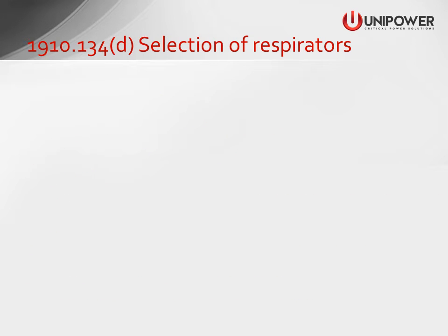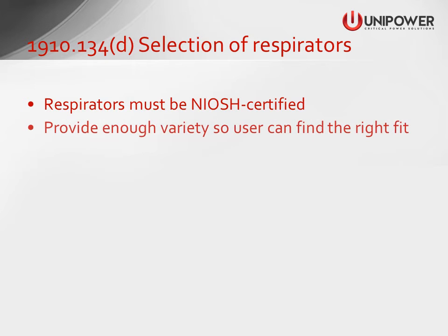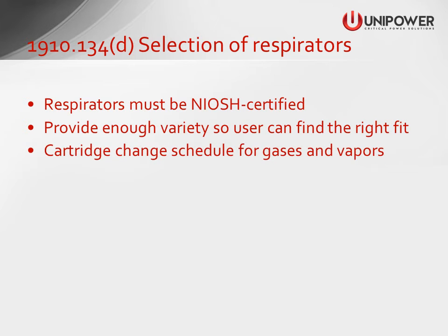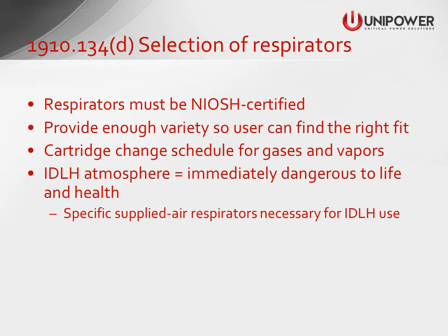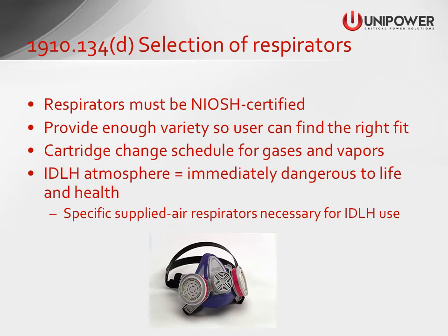Section 1910.134D speaks about the selection of respirators. Respirators should be NIOSH certified. The company should provide enough variety so the user can find the right fit. Cartridges should be changed on a schedule as used for gases or vapors. IDLH atmosphere, immediately dangerous to life and health atmosphere, must be specified on the air respirators necessary for use in these conditions.